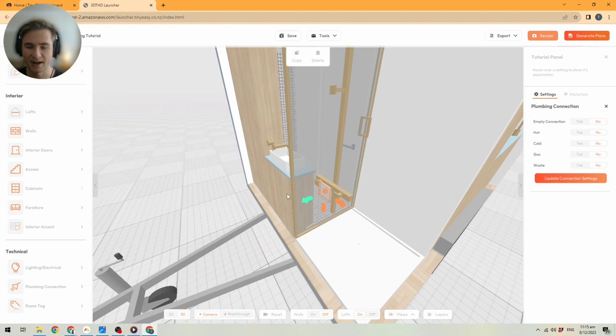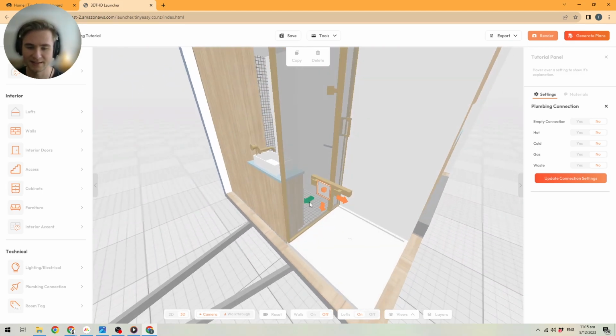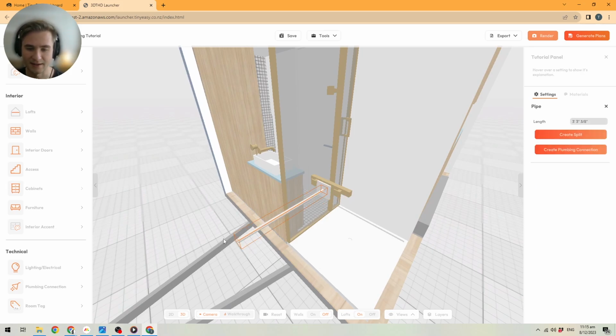So to actually drag a pipe, you will click this green arrow here, which starts drawing your pipe. So you left click once and you let go, and then a new pipe will follow your mouse cursor. And I will just drag it out until roughly here, which will just bring this out a little bit. And now you can see we can create a bend in this pipe. So we can go either up, down, right, or left, or we can actually change the length of the pipe by left click and dragging this orange arrow here. And this is if you've placed your pipe and it's not quite the right length yet, this is how you can change that. All right, so I'll just put it back to where it was right now.